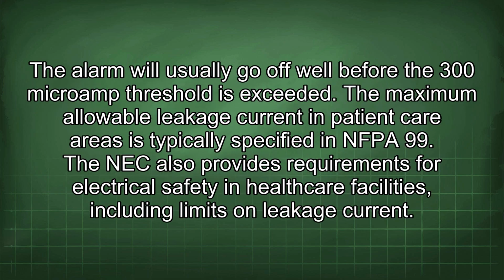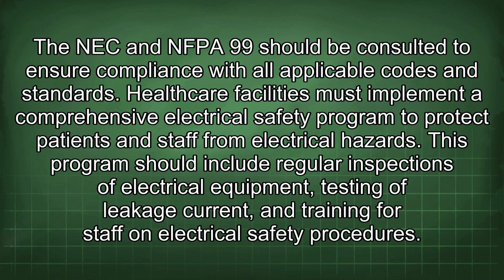The alarm will usually go off well before the 300 microamp threshold is exceeded. The maximum allowable leakage current in patient care areas is typically specified in NFPA 99. The NEC also provides requirements for electrical safety in healthcare facilities, including limits on leakage current. The NEC and NFPA 99 should be consulted to ensure compliance with all applicable codes and standards.